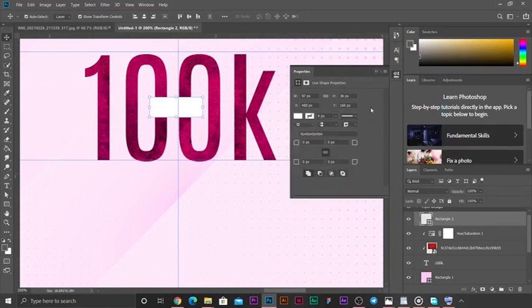The next thing we need to do is to adjust the edges and make it round. So one of the ways we adjust the edges, if you come over here, you see the panel where we adjust the edges of the rectangle. So I'll come over here and begin to move it. If you see, as I hover on this angle here, my cursor has changed to a hand with left and right arrows pointing at the edge.